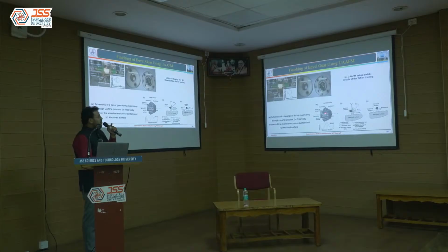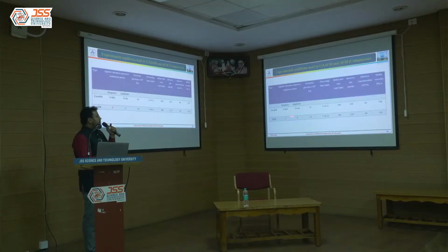This talks mainly about the abrasive particles, their penetration and oscillations, and their effect on finishing a bevel gear. So we have discussed one important parameter. As I said, by giving ultrasonic vibrations, it will minimize the processing time, meaning it will improve the finishing rate, right?